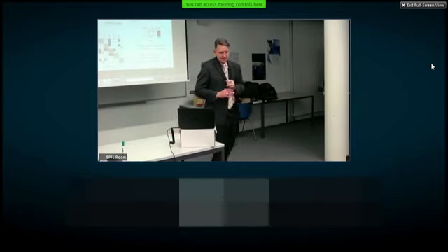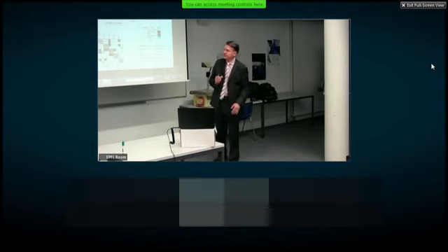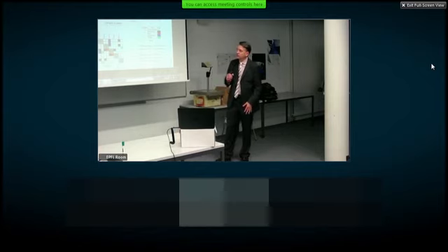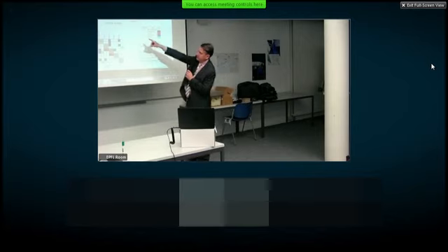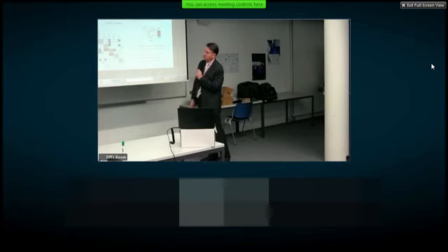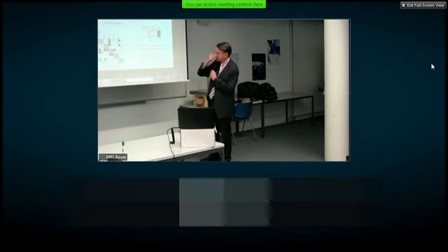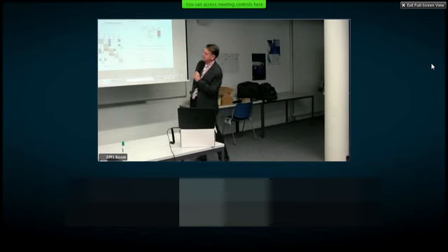So let me talk about DSM. Muriel was asking about DSM. DSM is a fairly recent method, from the last couple of decades, for making a map of your system that shows these interfaces explicitly. Here's a very simple example. This is a sample system with 5 components: a pump, a controller, a motor, a valve, and a filter. In this case, we have mass flow from the pump through the valve into the filter.